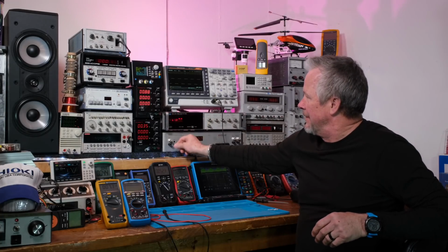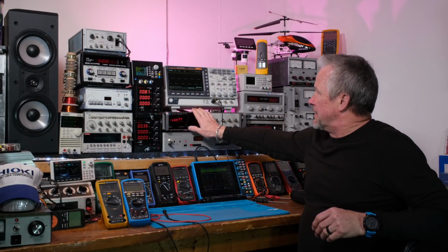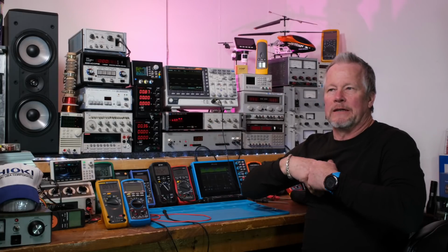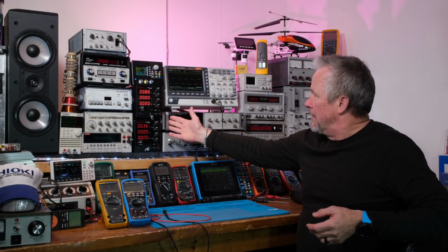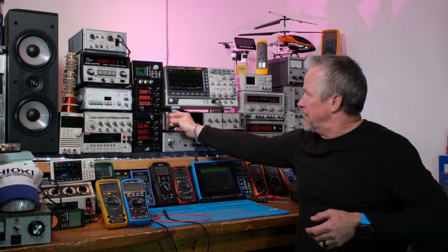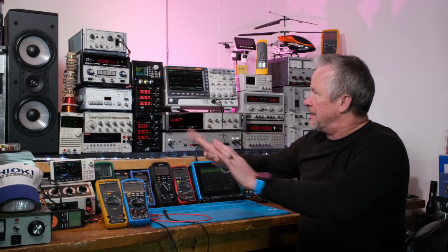But sometimes 2 prongs are the way to go, sometimes 3 prongs are the way to go. Anytime you have metal, it's 3 prongs. You need that ground. You want to tie that, even if there's nothing moving like a motor that could potentially touch that metal. Even if you're not concerned with that kind of thing, you still don't want any kind of leakage voltage, or you don't want 2 metal things you could touch.